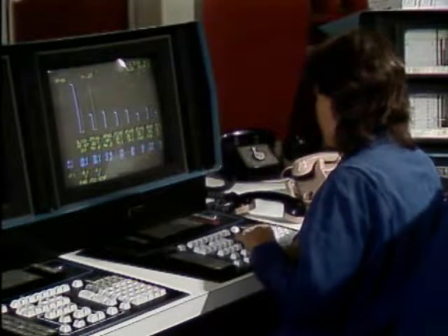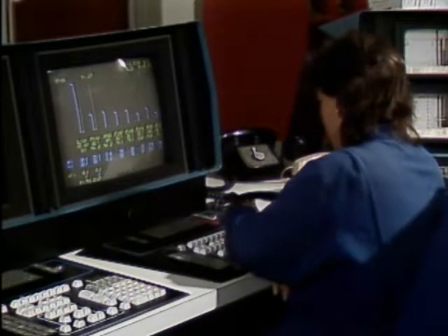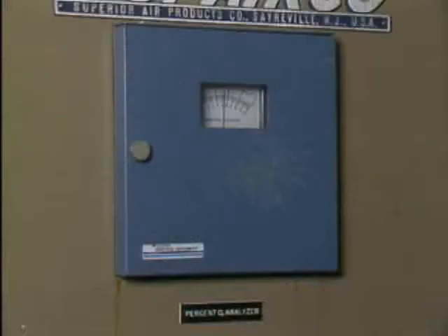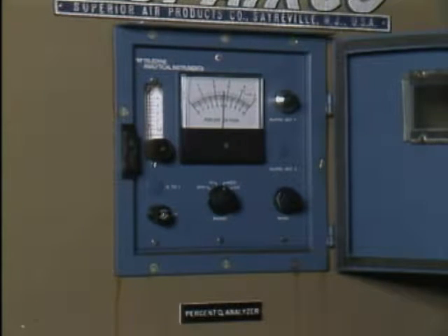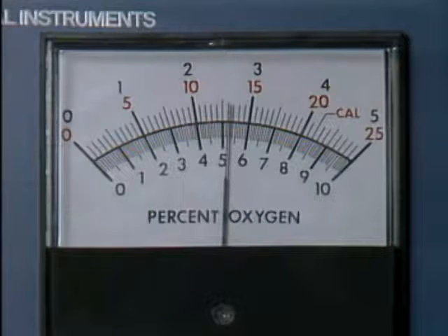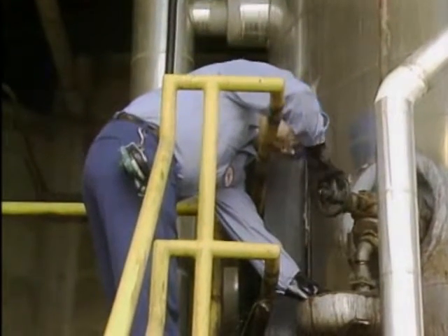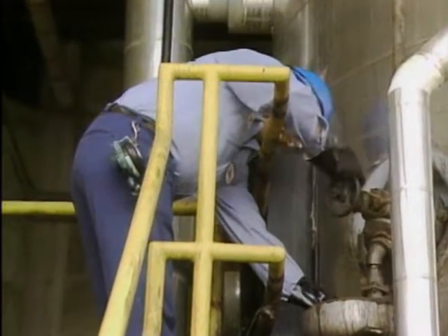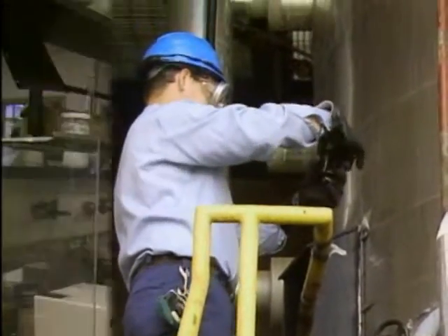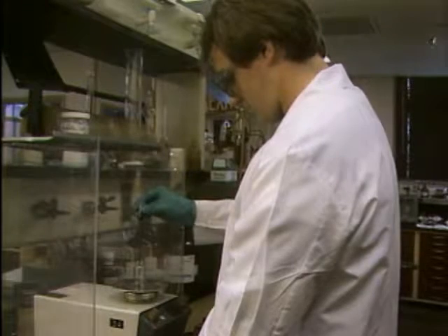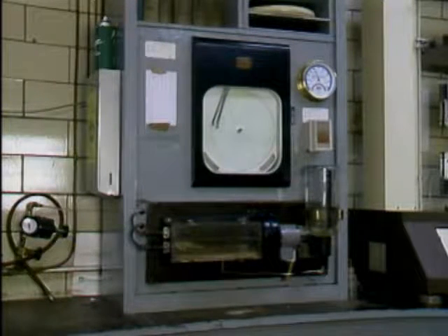Analytical variables are of value to operating personnel only if they can be accurately measured. Analytical variables are typically measured using instruments called analyzers. An analyzer measures and indicates physical or chemical characteristics that are based on the composition of a material. Analytical measurements can be obtained in different ways. One way is to take or grab samples from a process periodically, and then analyze them in a laboratory. Another way is to monitor analytical variables continually.